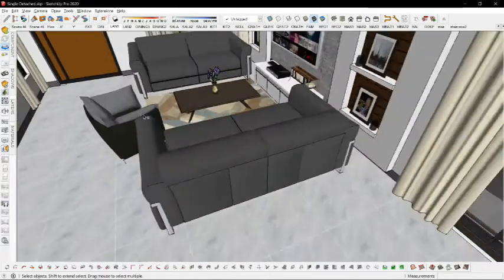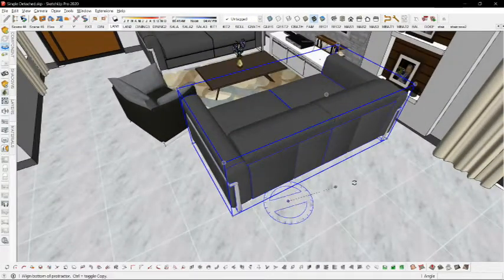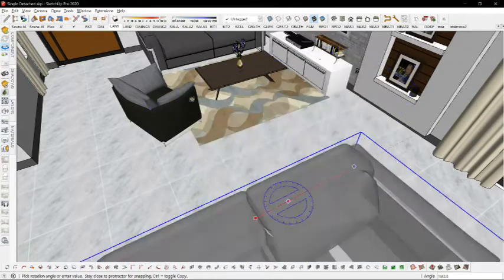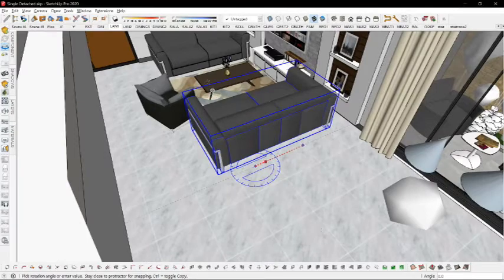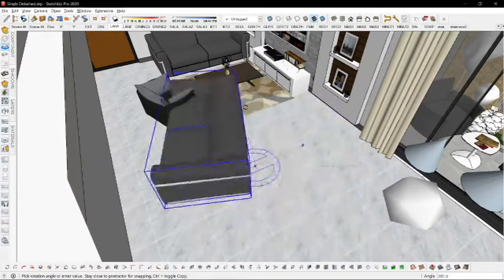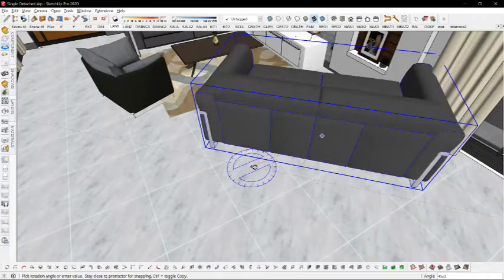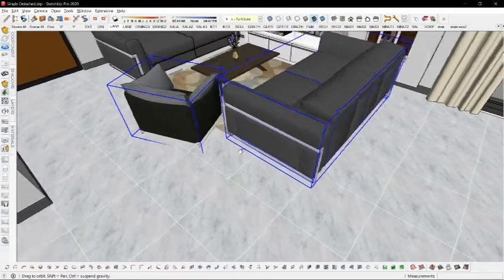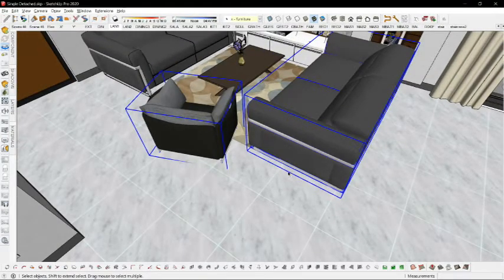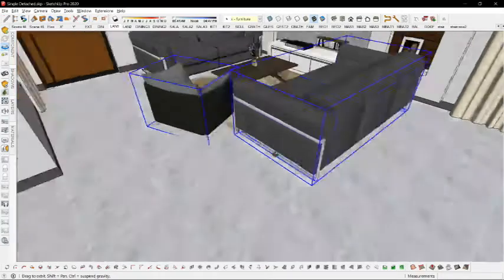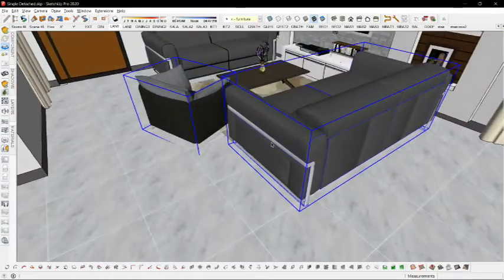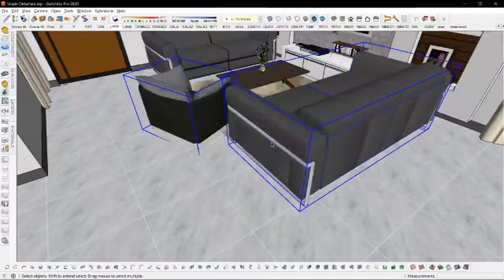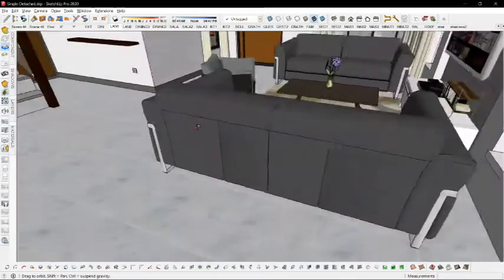Let's try to do it with this. Click one, left arrow, right arrow. So it tries to mirror it based on the vertex, or what you call this, pivot. The case is not true when you try to click on two different things. If I press Alt-Q, Alt-W or Alt-E, nothing happens. So press Alt-Z, X, and C for more than two groups or components.